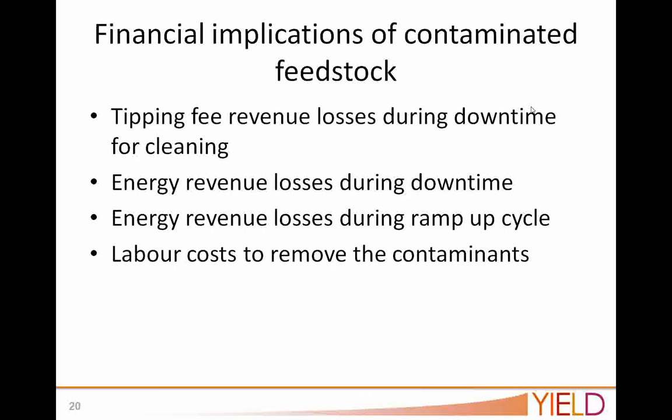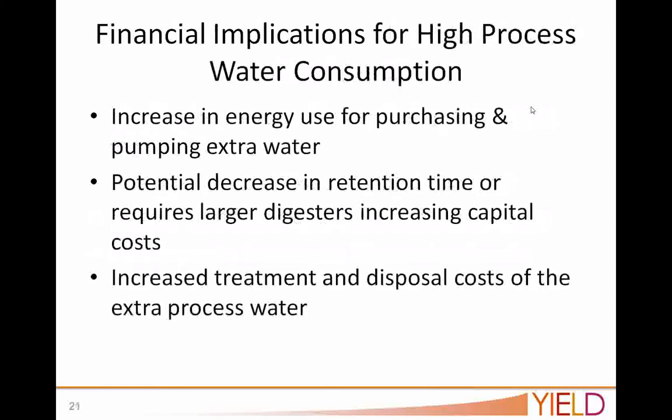A further complication is if you made a digester with a steel tank, you can't do that because of the risk of damage to the enameled steel, which is one of the reasons why we use concrete. We don't even risk designing a digester with a steel tank. Yes, it may save you money, but especially if you're dealing with this type of feedstock, I really don't recommend it and wouldn't do it. I wouldn't invest in it myself.